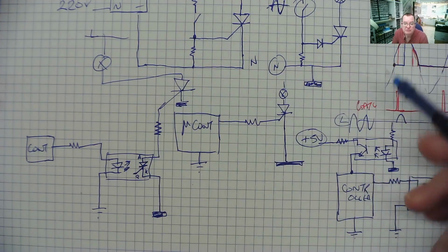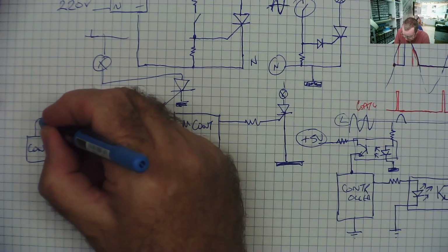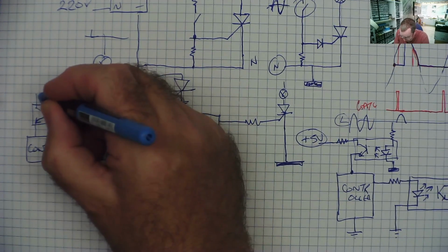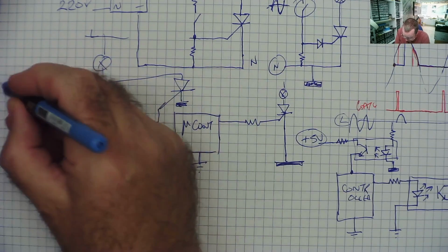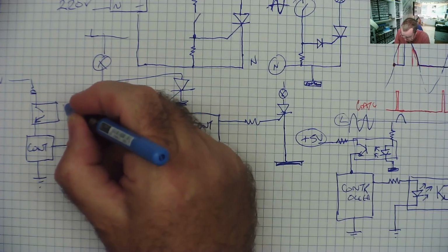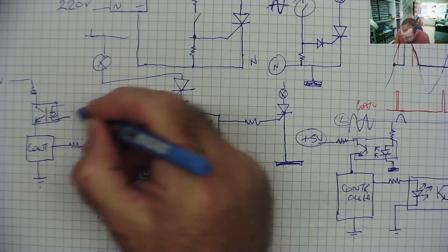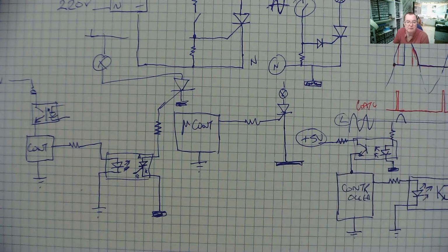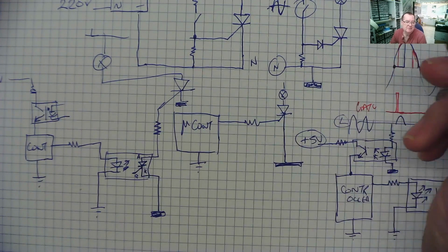This circuit will still have the zero crossing detection, so you will still have this here with a transistor usually in the opto isolator. This will still be there. 5 volts, safety ground, and the LED. So that will still be there, basically detecting the 0 voltage. This usually is an opto isolator which has a photo transistor inside it.